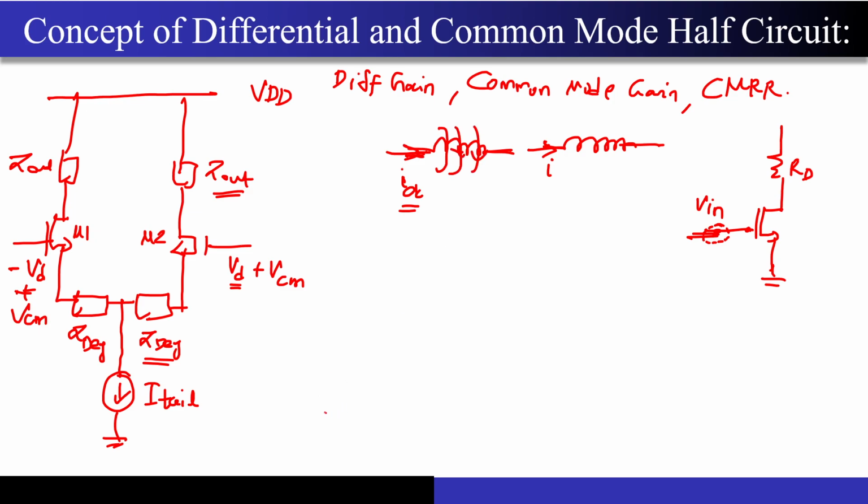And what is the chip area? So chip area can be something like, if you take two rectangular dies like this, something like 3 mm cross 1.5 mm. Correct. So the purpose of telling you is that what you are passing is time varying current. This will generate a time varying magnetic field. Now what is this? So this is another metal layer, maybe metal 1 or metal 2.